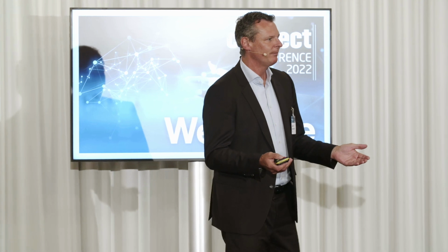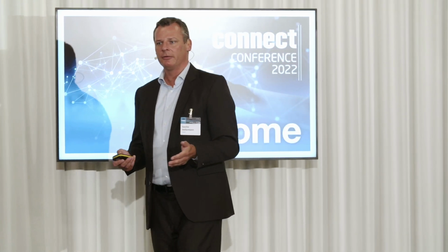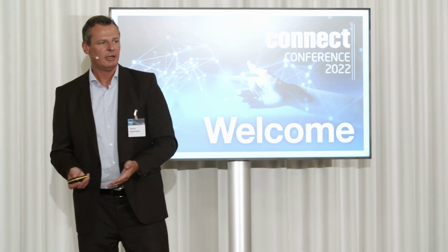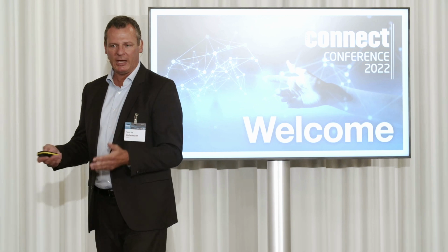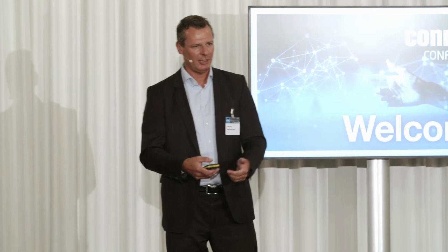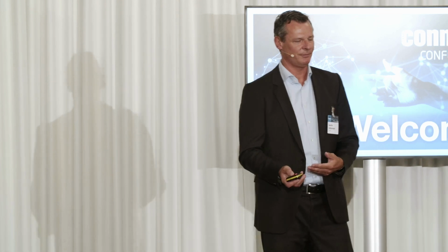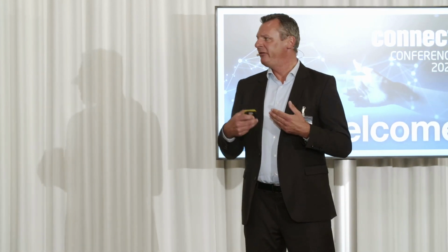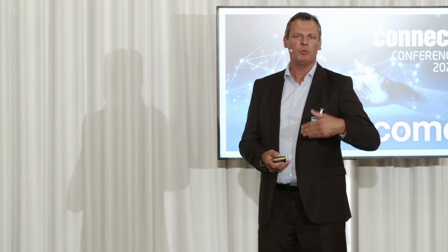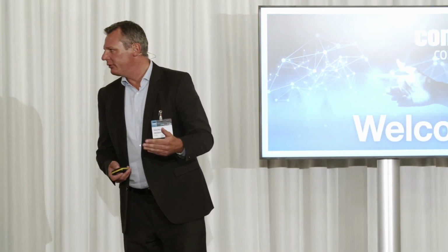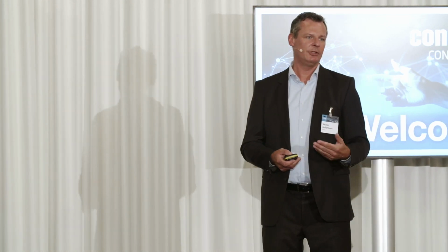No one is allowed to use the same frequency spectrum in the same area. A Wi-Fi network is based on public frequencies. Any smartphone, any other application, even the remote-controlled car of your son disturbs those networks. So if you want to run an interference-free network, a 5G mobile private network has way more benefits than a Wi-Fi network. That's why we said 5G meets the requirements for industrial IoT use cases.